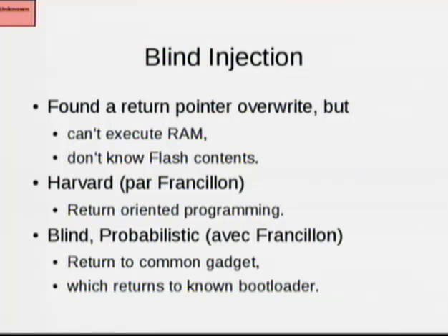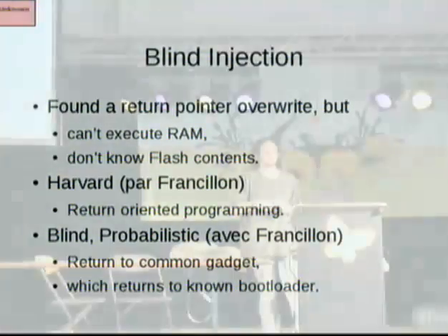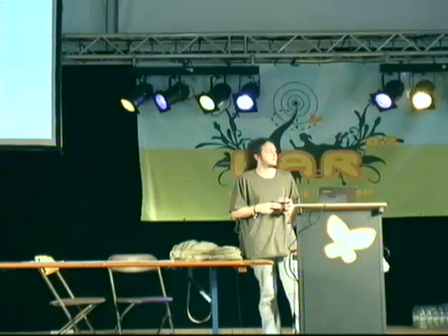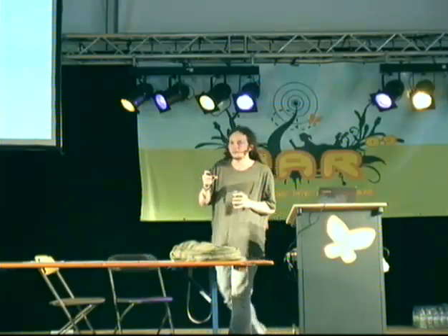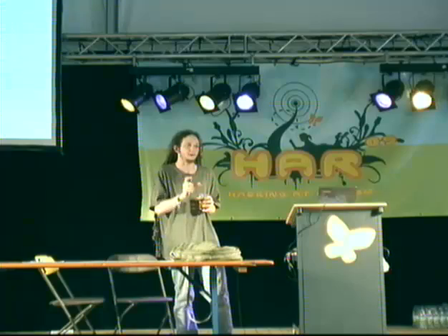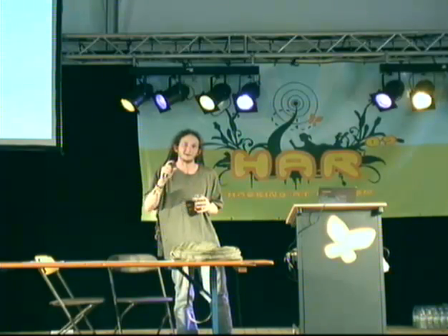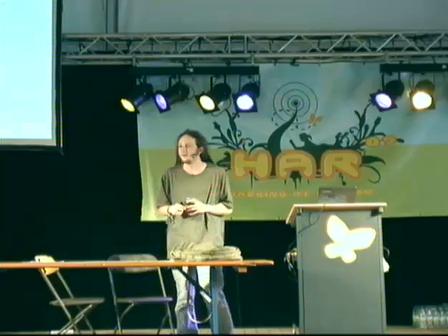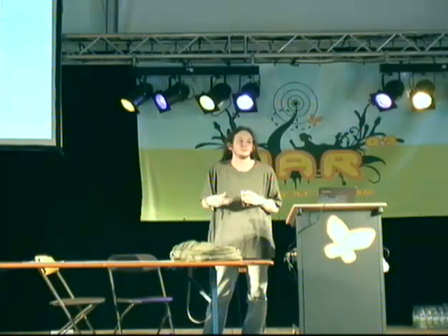So in our case, the compiler would open every function with push R11, push R10, push R9, push R8 to save the values in those registers before changing them. And then it would end with the opposite sequence. Pop R7, pop R8, pop R9, pop R10, pop R11, return. And the credentials to the master ROM bootloader were stored in register 11, which means that the fragment of code we wanted, pop R11 return, was actually the most common sequence of 4 bytes in all of flash memory. So it was very easy to find that location by guessing.